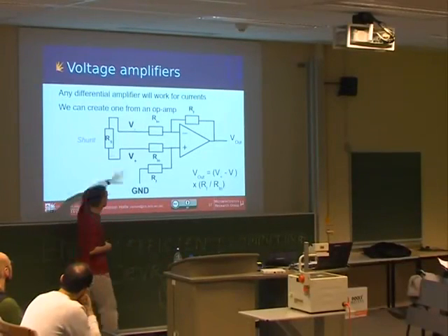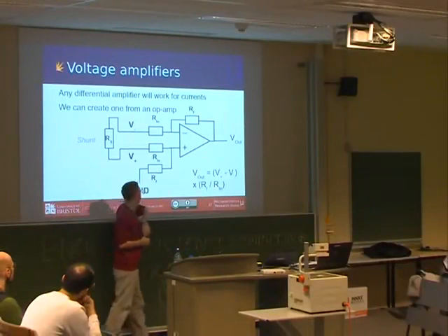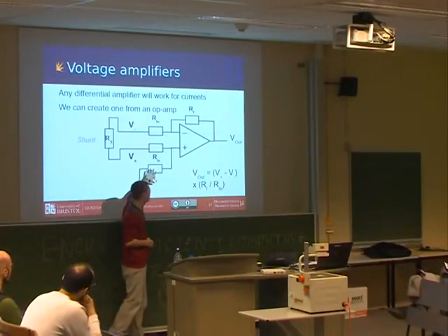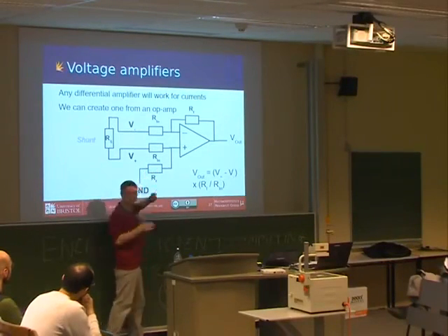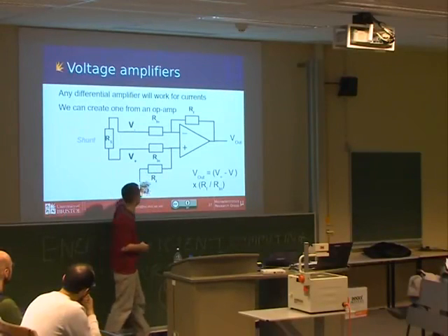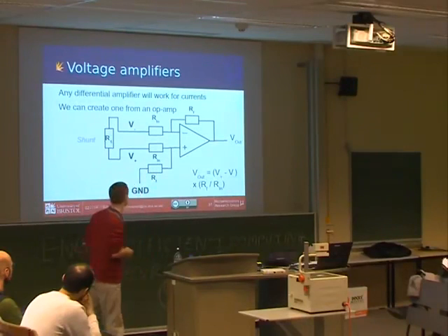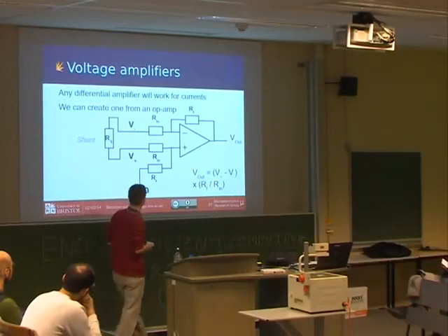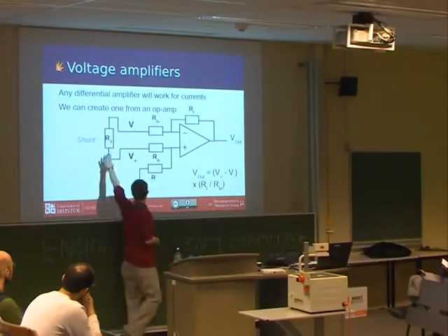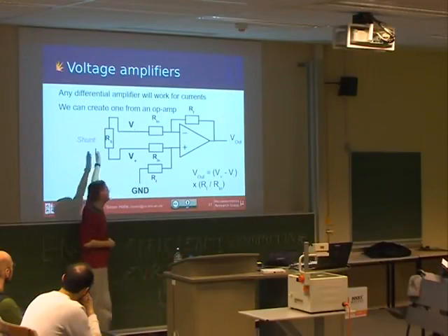which gives you, again, an amplification ability. And you can set these resistors, so for 50 times gain, I set this one here to 50,000 ohms, this one to 1,000 ohms. You can find that in any textbook. And then what we do is just take the sense resistance as part of that power supply.